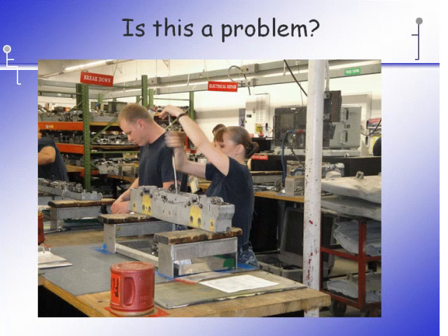So what's wrong with this picture? This woman is using a speed wrench, so she's using a wrench that has a bent angle in it so she could speed around quickly, and she's holding it on the top, pressing it down so it doesn't lift off the nut.